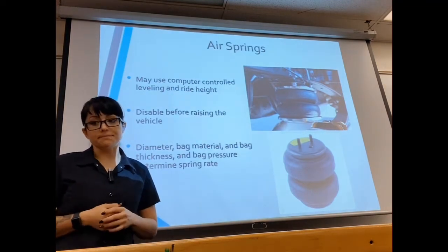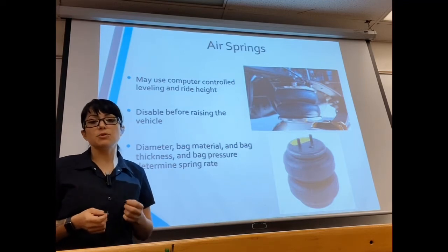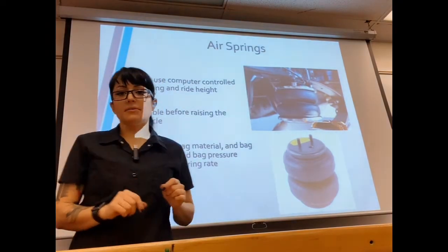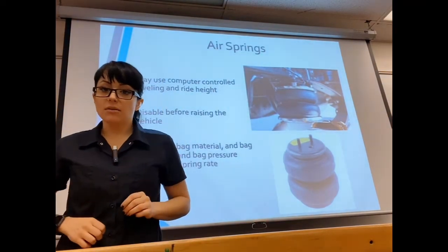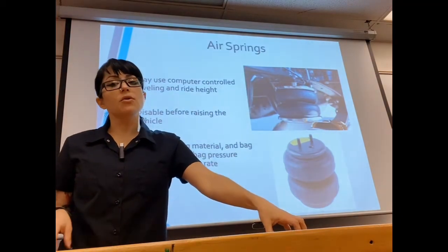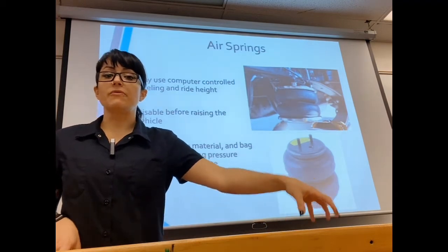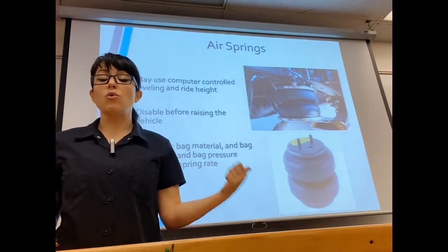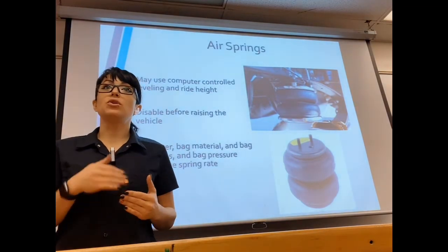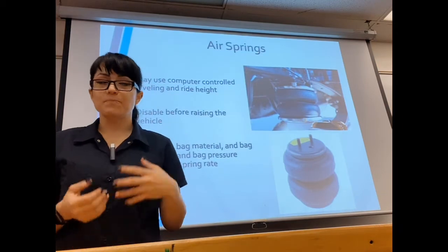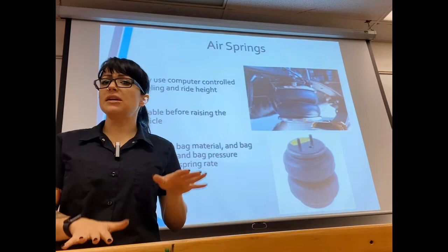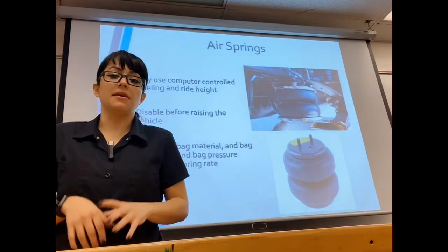Now, if your vehicle comes stock with air ride, meaning you can change your ride height from the push of a button, that means that is computer controlled. Meaning that you press the button, it asks the computer, the driver would like to do this to the air ride, and the computer is going to send a signal to either the compressor or some valves that are going to inflate or deflate those airbags for you. Sometimes there are these automatic settings that will change ride height based upon your speed and things like that. As well as it will see potential driving habits and be like, oh, we need to lift the vehicle or lower the vehicle.